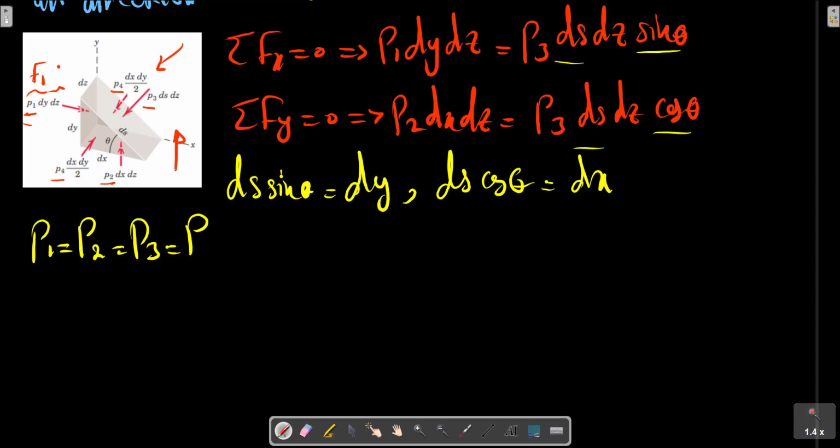In this analysis, we need not account for the weight of the fluid element, because when the weight per unit volume is multiplied by the volume of the element, a differential quantity of third order results, which disappears in the limit compared with the second order pressure force term.